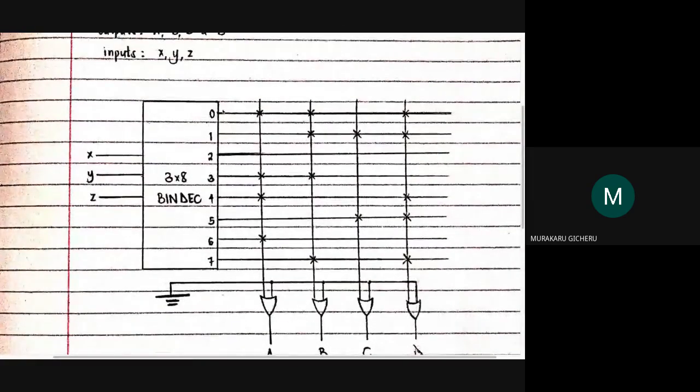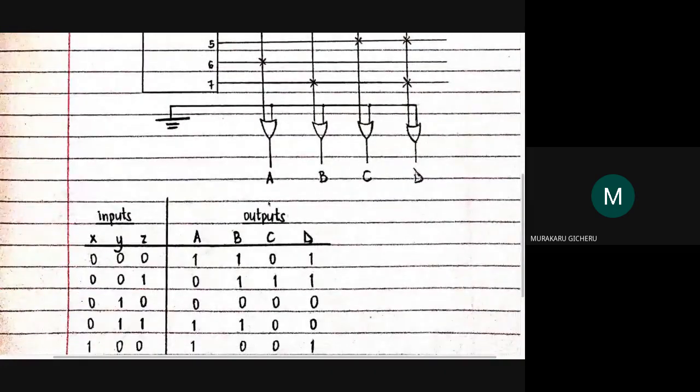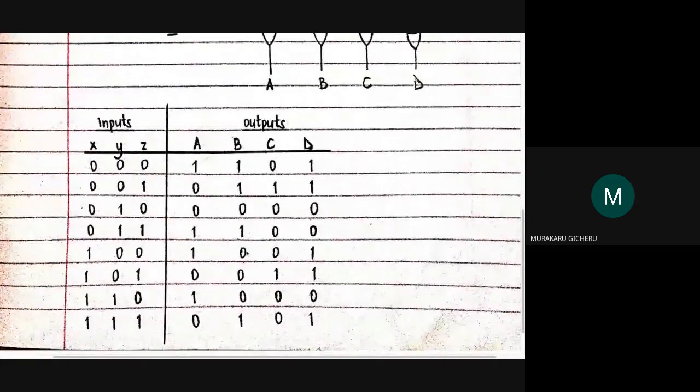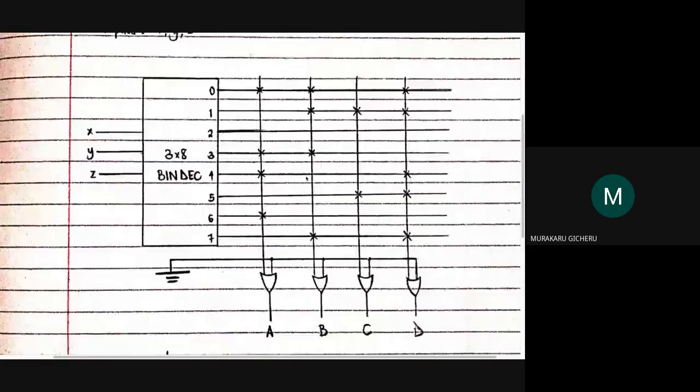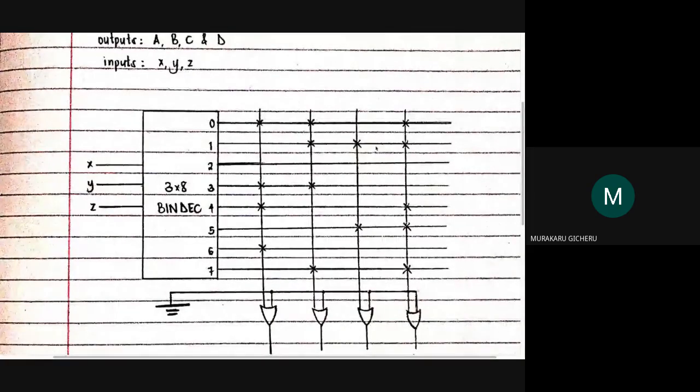So if we go to address 0 and read what has been stored there, which is manifested as these crosses, where each cross represents a 1 and lack thereof represents a 0, the data stored in address 0 would be 1, 1, 0, 1. You can see that? Yes.